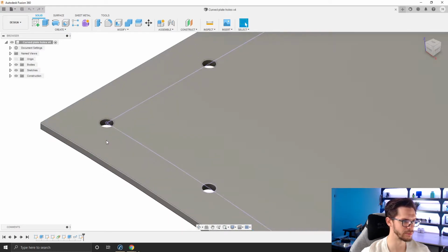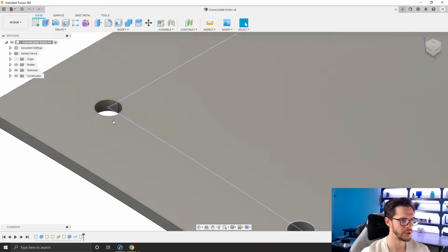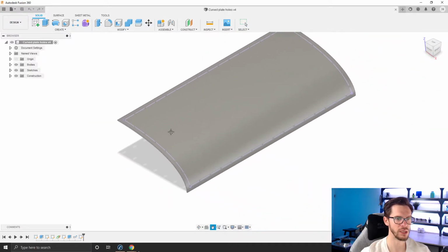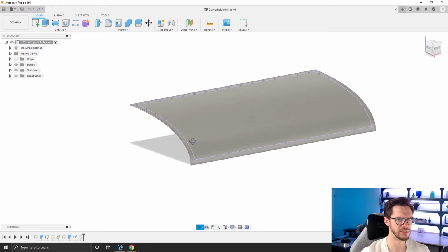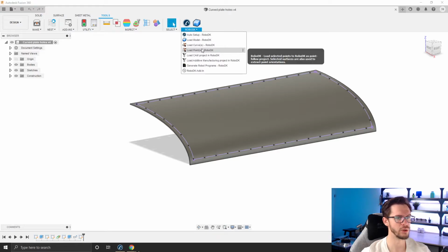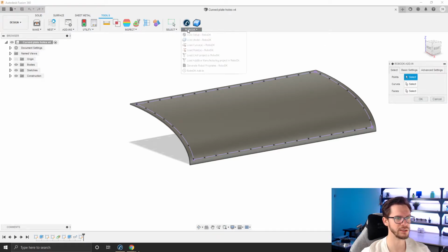I created, really in the CAD software, one point in the middle of each hole. I do that in SolidWorks in like 2 minutes, and for this program it took me a bit more time. I'm pretty sure I just don't have the right method. But anyway, if you go to Tool, you can go load point this time, so Tool, load point instead of loading curve.